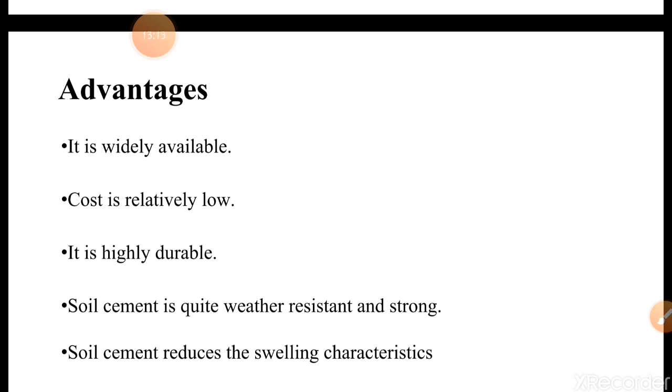It is highly durable. Once we mix the cement with the soil, properly compacted and cured, the durability of the soil will be higher. It will sustain for longer durations. There are chances that some chemicals, once you add them to the soil, will wash out along with the water during rainy seasons. That's why they will not give us the required strength. But cement is not like that. Once the hydration process is generated, it will be a permanent structure. It will bind the particles together so that the particles don't go away from each other.